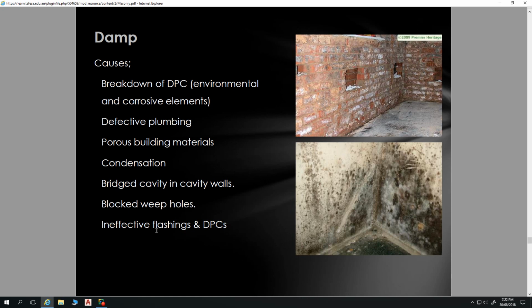That warm, moist air, when it comes in contact with anything cold, loses its moisture, and then that moisture is deposited as condensation on your walls or your ceiling. And from that condensation, in severe cases, you can get mold happening. And mold is bad for buildings, but it's also really bad for people. There are plenty of health side effects to living in a moldy house.